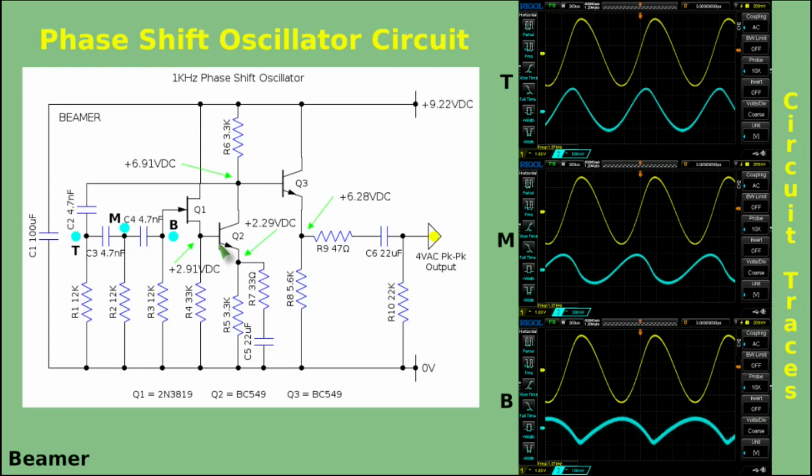If we jump forward one section and go to the voltage gain, you can see that between the base and the collector there is always a 180-degree phase shift. So as this feedback is feeding the beginning of this network, it is 180 degrees. Well, if you add 180 degrees across the transistor and 180 degrees across the phase shift network, you end up with a number of 360 degrees or 0. So this circuit is in a sense self-feeding. If you apply gain to that type of circuit, at some point you reach a gain where the circuit will start to oscillate. That gain is set here.